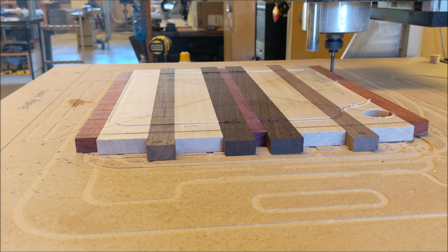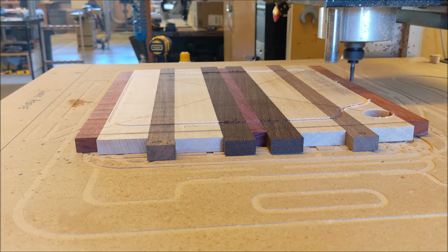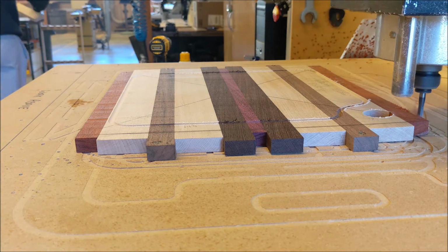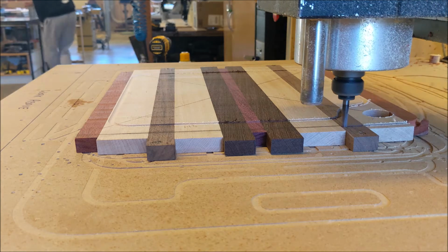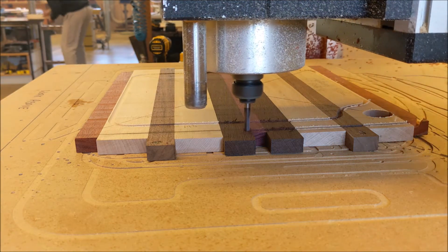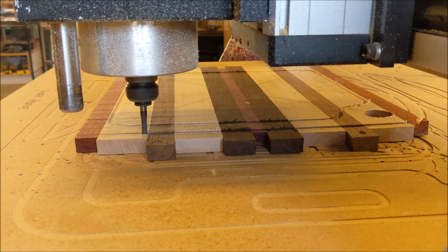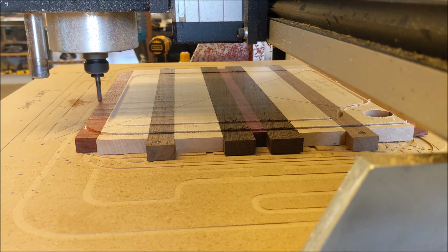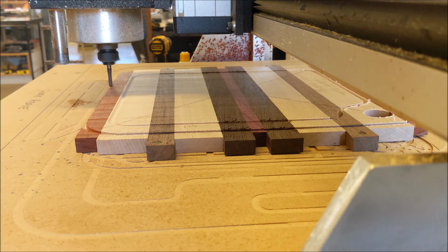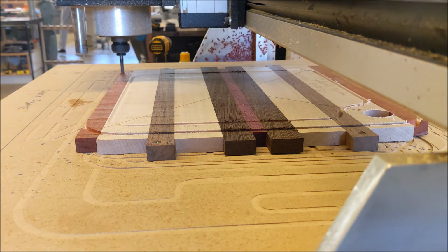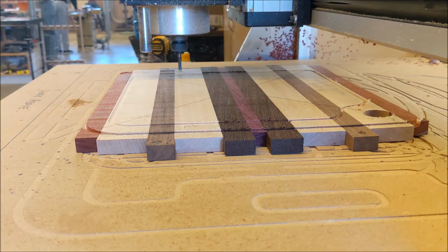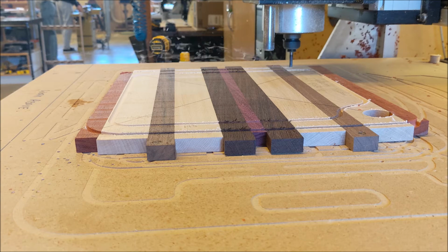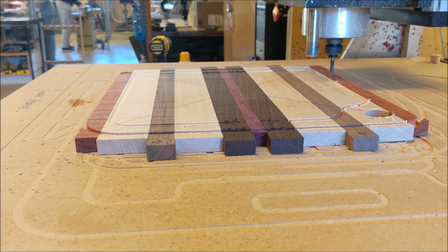Now that it's cutting out the hole, now it's going to go over and cut out the part itself. A couple things we're going to talk about here is direction of travel and compensation type. Look at that cutter or the router bit. It is on the left side of the line. That is called left hand compensation, and it keeps it outside of the part. I am also traveling clockwise around the part, and that's going to give me a climb cut. When I cut the hole out, I had left hand compensation, but I was traveling counterclockwise, which kept it inside of the part. So that's compensation type.